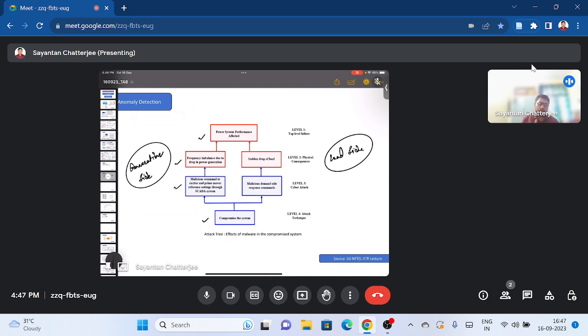Suppose there are no changes made from the operator's point of view, but there are still frequency deviations occurring on the generation side without any load variations. That would deliver information that there has been some attack, where the system measurements, generation values or set values may have been compromised, even though no changes were made from the operator's point of view.